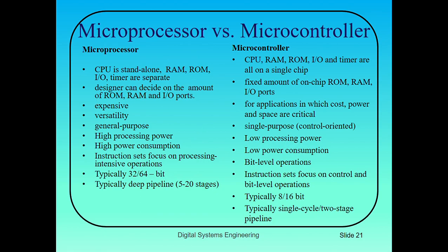Microprocessor versus microcontrollers. We will discuss the difference in detail here. The key difference between both terms is the presence of peripherals. Unlike microcontrollers, microprocessors have no built-in memory, ROM, serial ports, timers, and other peripherals that constitute a system. An external bus is required to interface to peripherals.